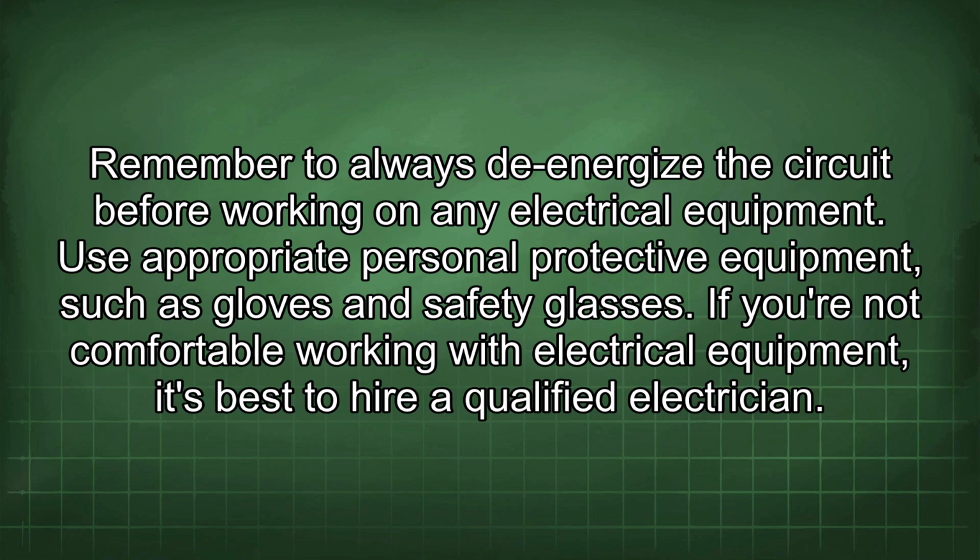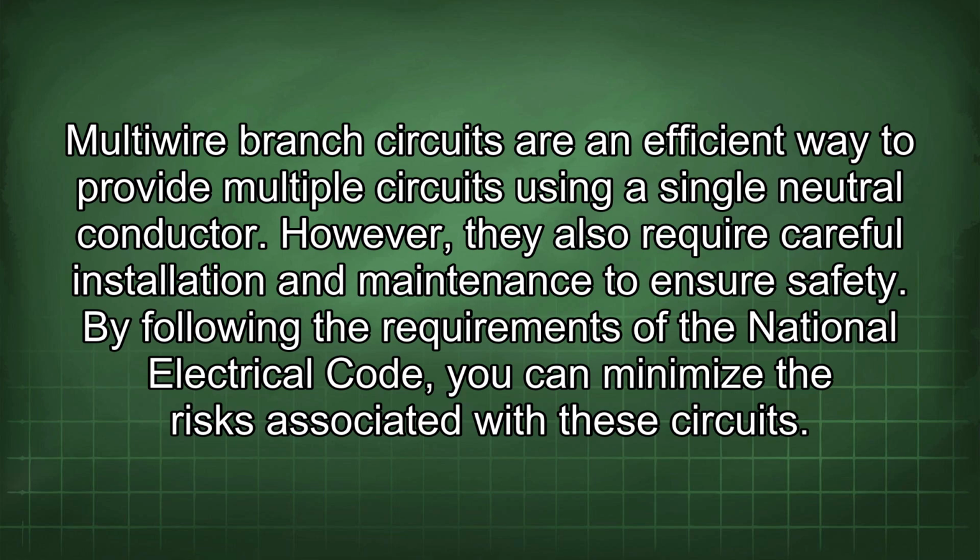Remember to always de-energize the circuit before working on any electrical equipment. Use appropriate personal protective equipment, such as gloves and safety glasses. If you are not comfortable working with electrical equipment, it's best to hire a qualified electrician. Multi-wire branch circuits are an efficient way to provide multiple circuits using a single neutral conductor. However, they also require careful installation and maintenance to ensure safety. By following the requirements of the National Electrical Code, you can minimize the risks associated with these circuits.